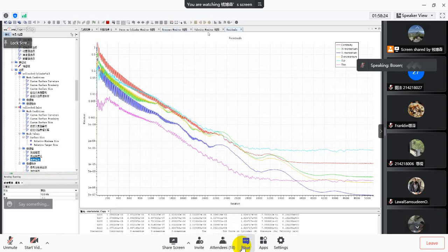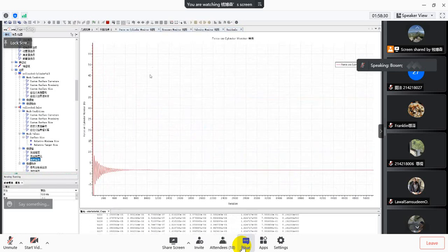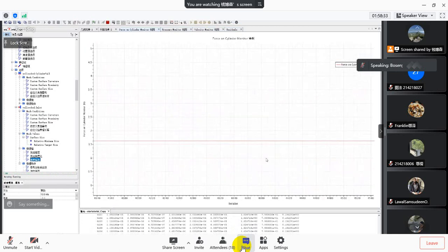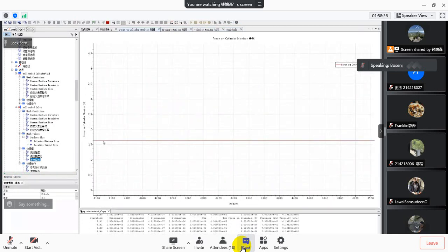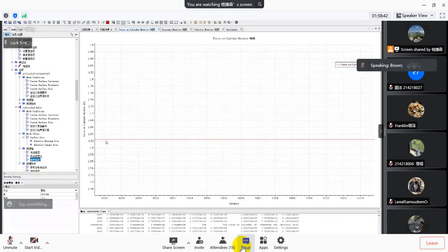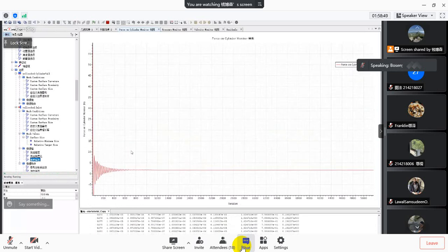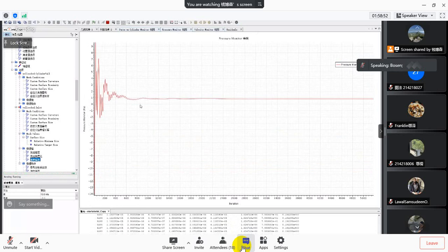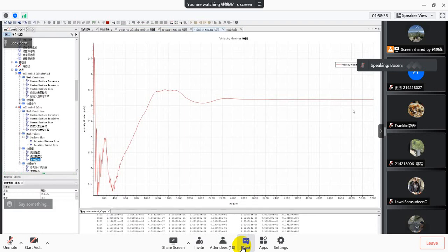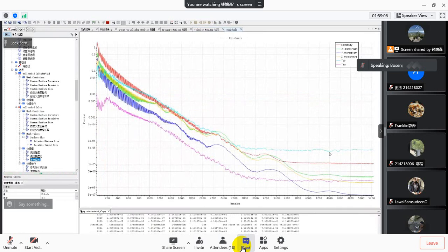And if we look at the velocity monitor, pressure monitor, force monitor, what we can observe still has the same rule. You can move on your rollers on the mouth, so you can see the force distribution. We can see the force is barely moving. It's getting very, very stable. The pressure is getting stable, and the velocity is getting stable. Also the residuals are getting much, much smaller.